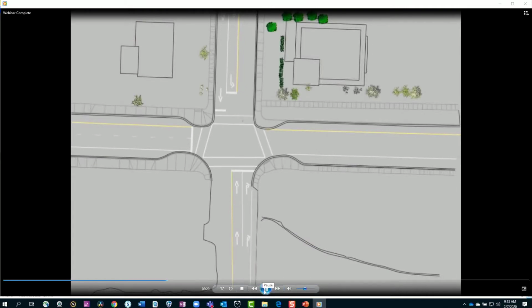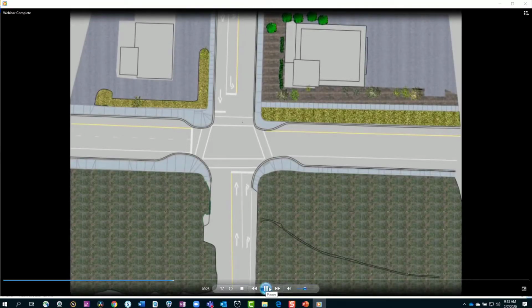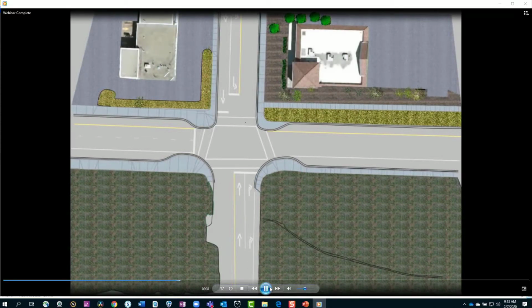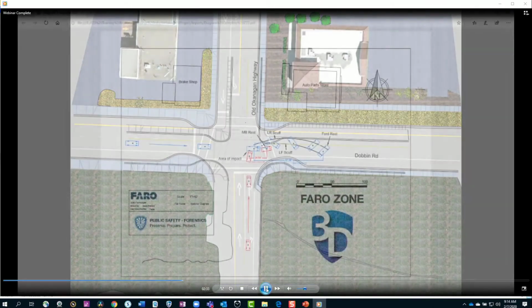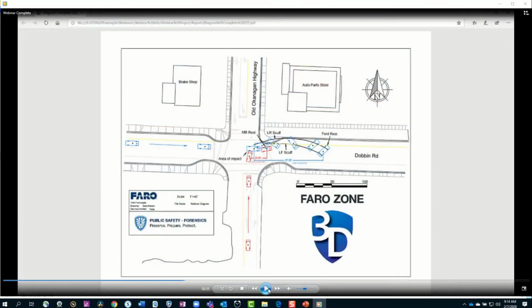And speaking of visual information, how detailed do you want to get in your diagram, folks? 3D foliage, maybe ground textures, maybe sidewalk textures. You can add them all. Even snapshots of the buildings from your scaled Google map to really fill things out. And that brings us to this, our first of 4 deliverables, a to-scale crash diagram. Now, I know every organization does things a little differently. Your annotations might not be in the middle of the street like mine are, but for the most part, this is the kind of deliverable that many of our customers look for. And we got it from that drone photograph.